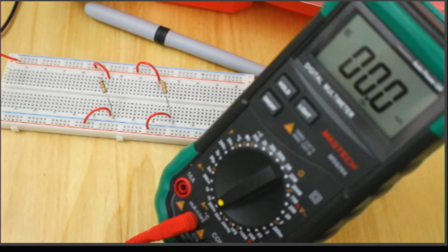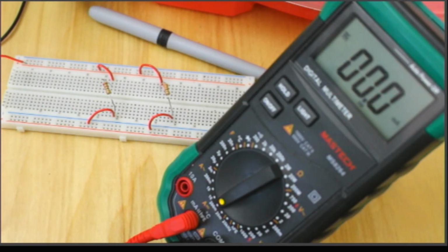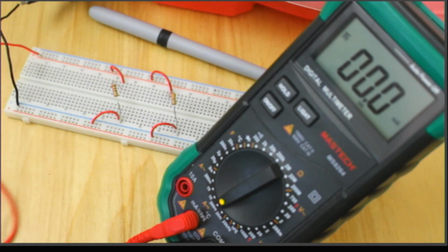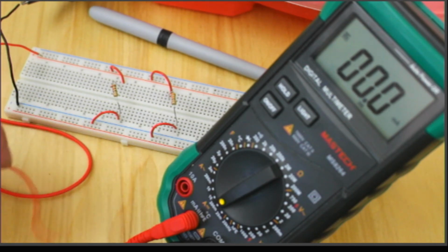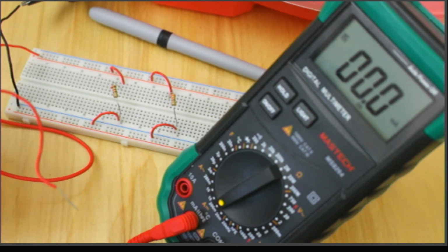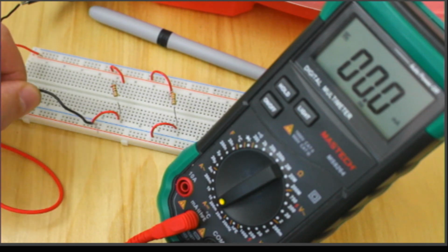All right. So there I've got it in, I'm measuring in milliamps, DC amps. And so I'm going to go ahead and connect the actual circuit. And so now it is live. Okay. It is running right now. So I have attached some alligator clips to my probes, and then on the end of my alligator clips I have a little piece of wire, and so that's where I'm going to put my current meter leads in. Okay, and so this red one is my red lead, and this black one is my black lead.